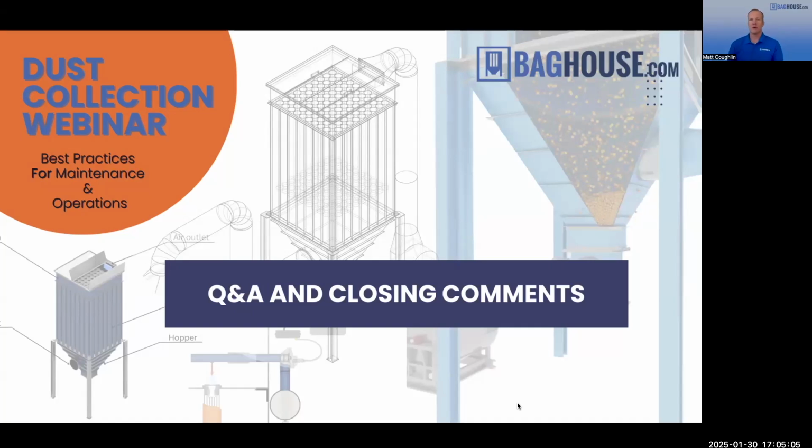So that's certainly important if you want clean, dry air in there. And if you have high temp dust, you want to make sure that you keep it high temp through the entire system, including through the baghouse. If you have cold spots in your ductwork or in your hopper or your baghouse, you run the risk of that hot dust dipping below the dew point temperature, where it turns into condensation and moisture. So if you have to deal with hot dust, you need to use insulation and, if necessary, supplemental heating around your baghouse and your ductwork to avoid those cold spots. Once the dust is out of the baghouse, you can let it cool, but while it's in there and in the ductwork, keep it hot.